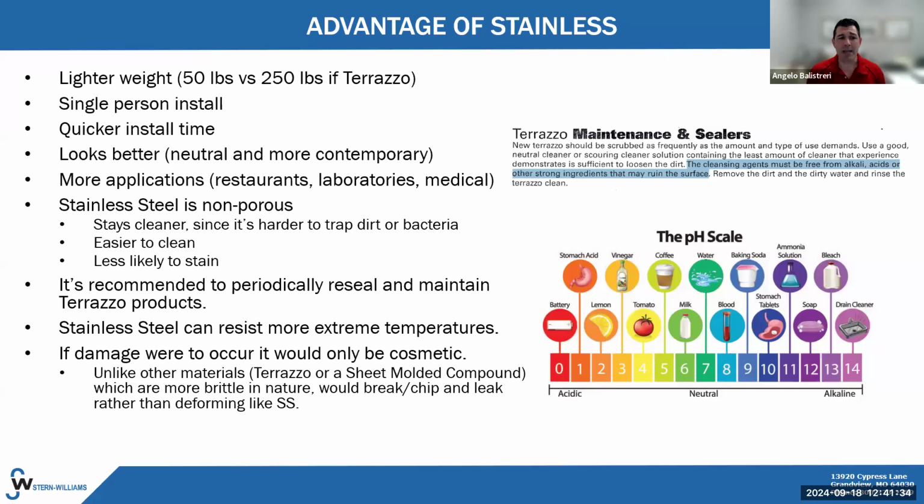Stainless steel doesn't have any of the porous stuff that you get with a concrete terrazzo base. That concrete terrazzo, as we all know, has micro pores, many of them probably not noticeable, but those are there, and that can lead to, depending on what you're utilizing it for, a little bacterial growth depending on what you're pouring into the mop basin. If you're not sealing it properly, you're not taking care of your terrazzo properly, it can lead to additional issues. With the stainless steel, we're pretty much taken care of with that particular material.